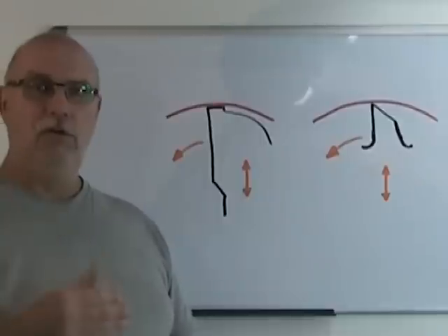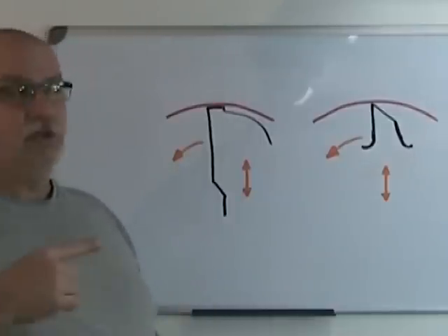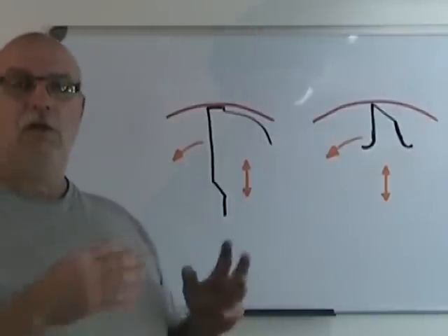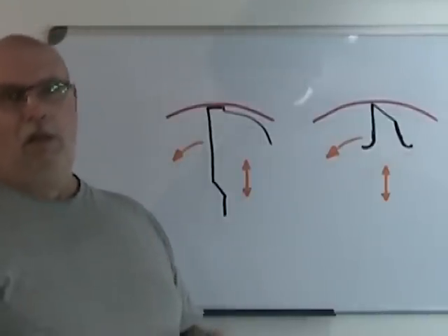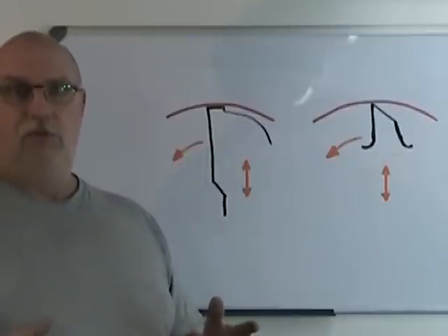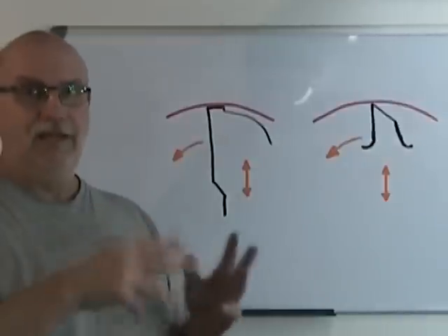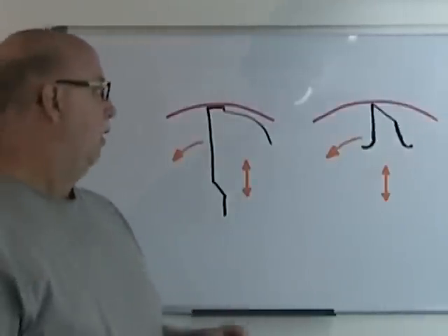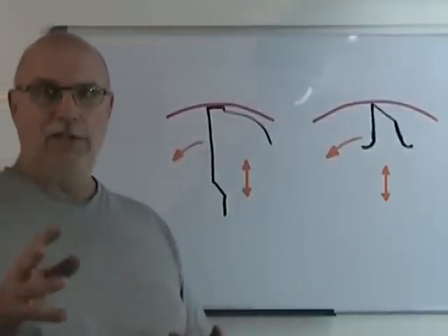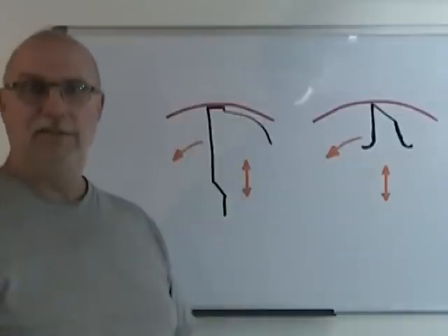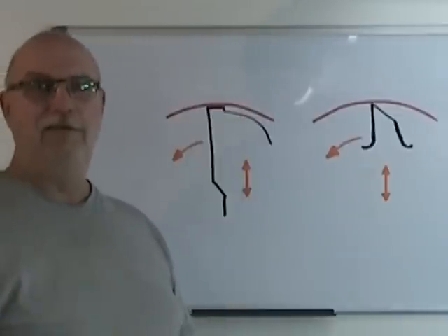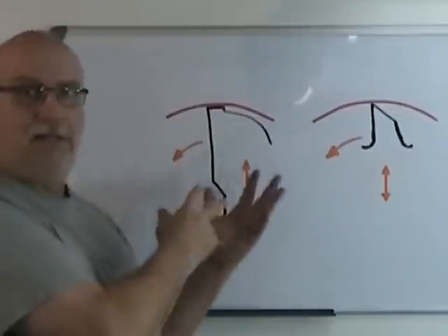So if you're putting coolant when you're drilling, you have to try and get it into the hole to cool your tool down. And if not, well, retract the tool as quickly as you can and cool it down with coolant. I hope that answers your question, Jim, and I hope it's nice up in Groenland. I'd really like to visit there someday. So let's get back to this.